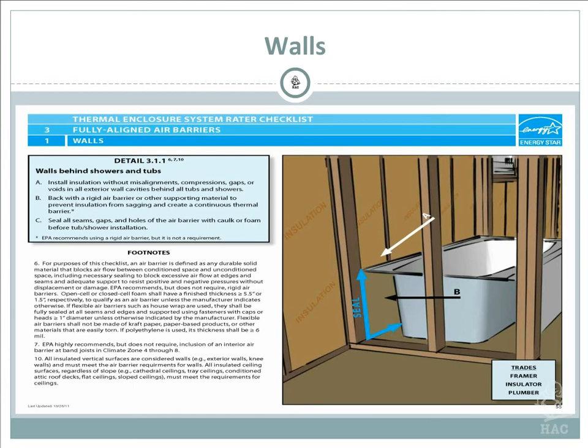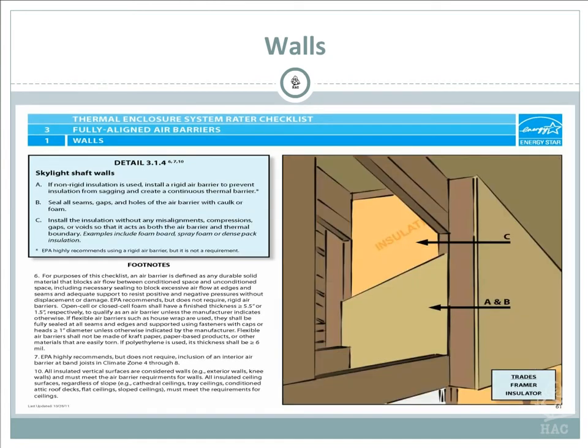So this is one that you'll always get caught on if you don't watch it. Again, we talked about skylights. With a skylight, you usually have sheetrock coming down. So you want to insulate that skylight, depending on what region you're in. I would just put a 4-inch or 3-inch foam board, bead board, on that, then you can cover it with sheetrock and seal that up.